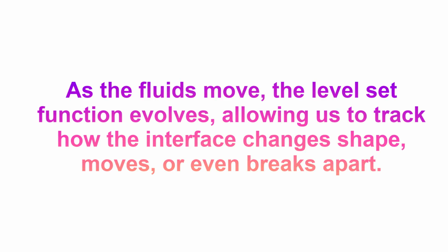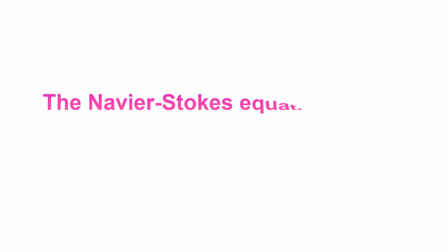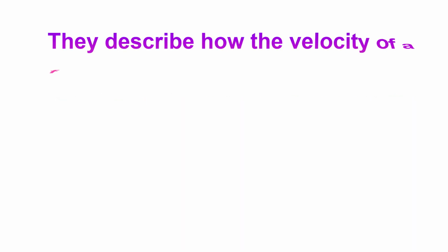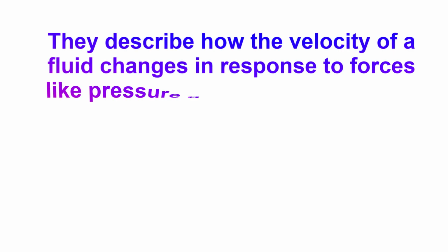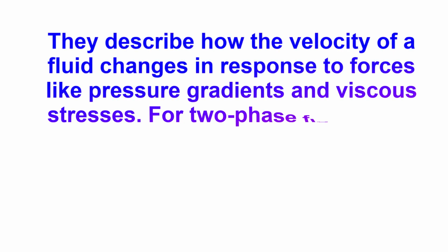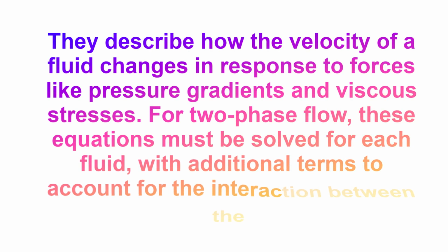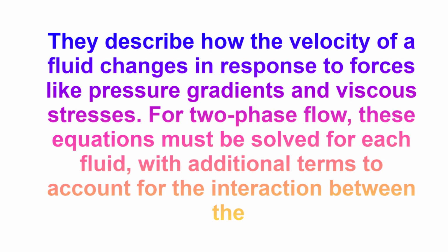or even breaks apart. So if we talk about the Navier-Stokes equation, the Navier-Stokes equations are the fundamental equations of fluid dynamics, as you all might know. They describe how the velocity of the fluid changes in response to forces like pressure gradients and viscous stresses. For two-phase flow, this equation must be solved for each fluid, with additional terms to account for the interaction between the fluids at the interface.